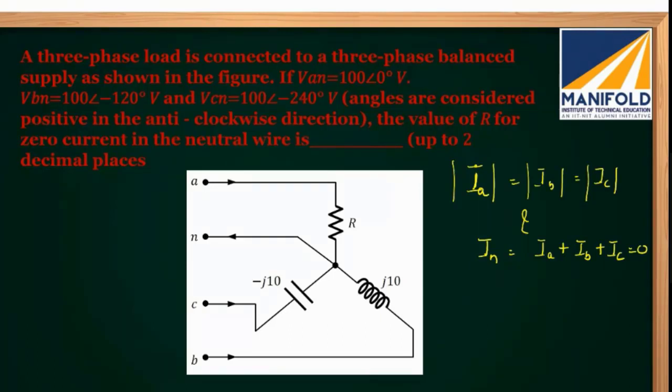However, if you see the load, in one phase the load is a resistor, in another phase it is an inductor, another phase it is a capacitor. The loads are unbalanced. If any one of the impedance parameters is different in the three phases, then the system is unbalanced, because the currents won't be balanced. The impedances in all three phases should be the same.